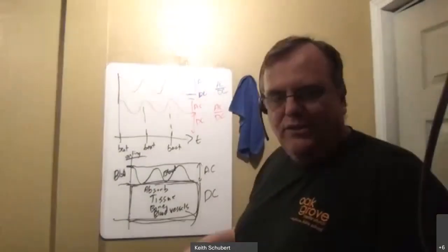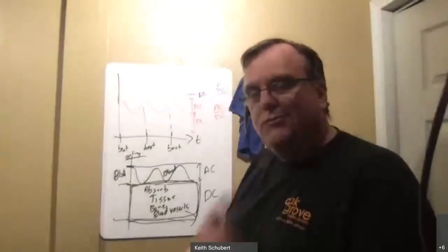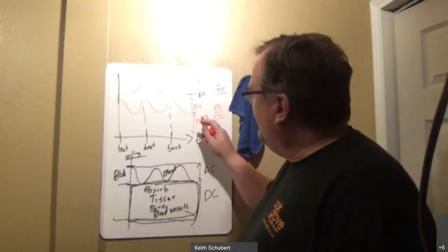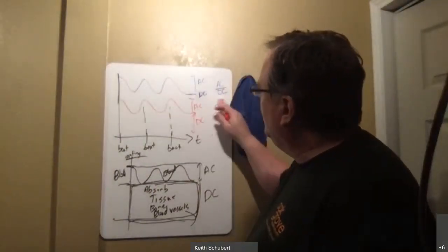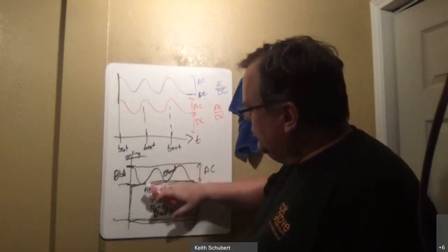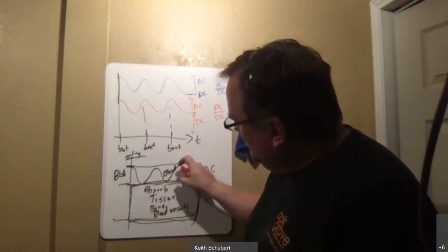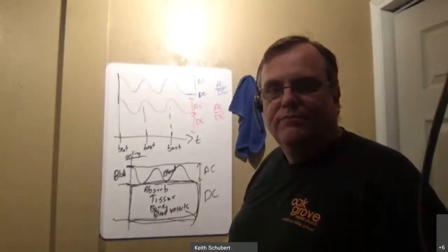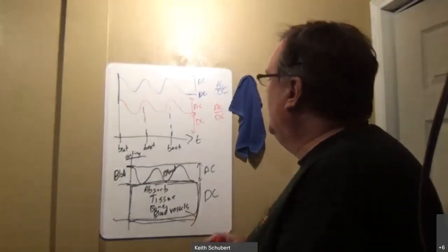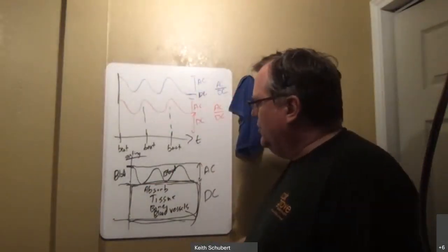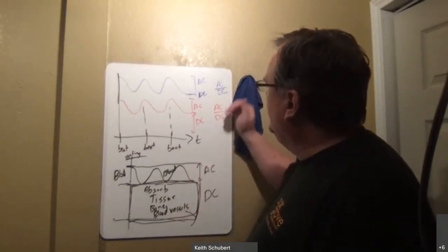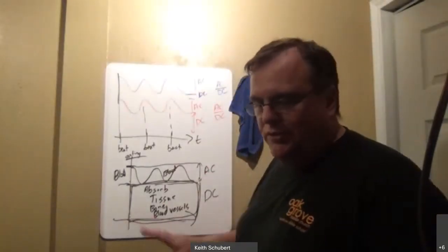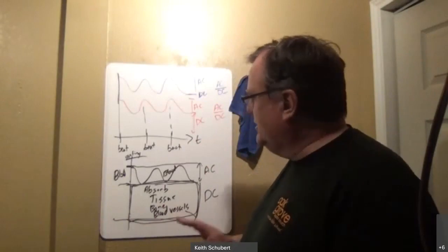By dividing by it, I'm essentially dividing by the amount of light that actually reached the blood. If that makes sense to you, right? So dividing here by the DC value is in essence modifying my I0. So I'm just measuring I0 and I for the amount that's passing through the blood. Okay? So that ratio now gives me what I've got for each of these frequencies of light. And now all the other tissues and everything else have been removed, so I'm just dealing with that portion.